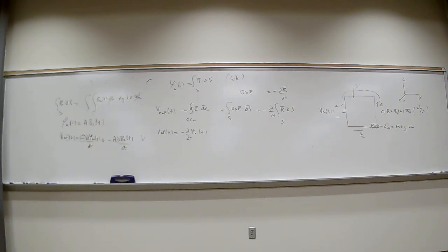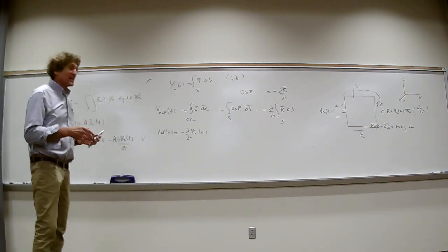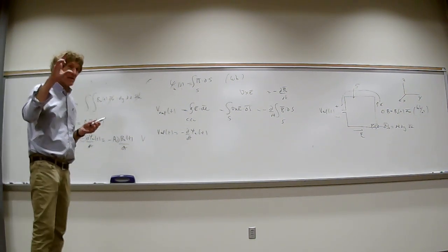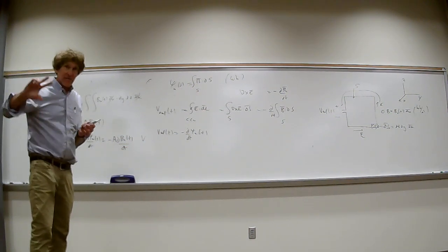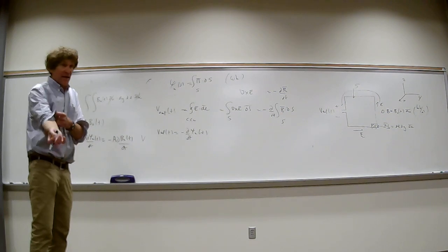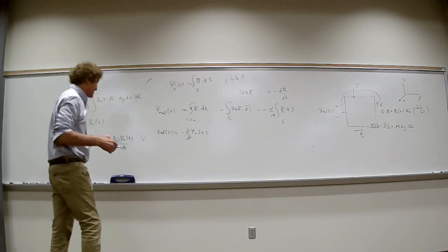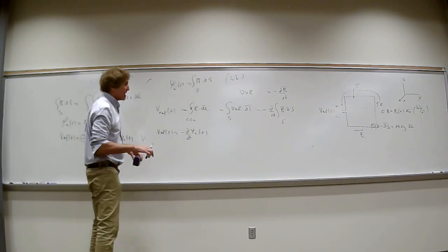That's why transformers have to have time varying current and voltage to either step up or step down a voltage and current. You all with me? That's very important. You can't do them for DC. You can take DC current and chop it, basically causing a transient effect, and then put that through the transformer, but you can't just take DC and change the voltage.